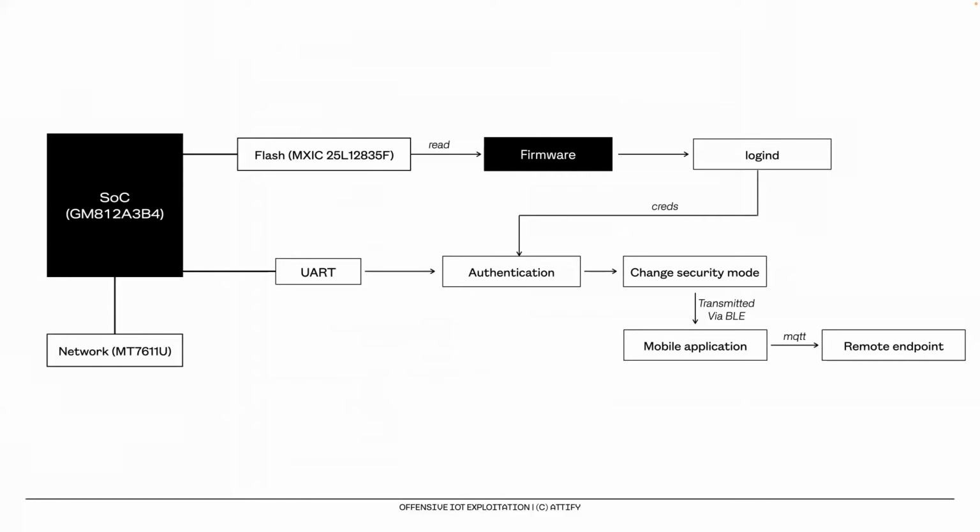So the SoC, let's say, has an exposed UART endpoint. UART is one of the interfaces that we'll see very shortly, and it gives you access to the device's root console, boot up logs, and these kinds of things. So let's say we have a UART interface that's coming from the SoC, and when we connect to the UART interface, it asks for an authentication. So it asks for a login and password.